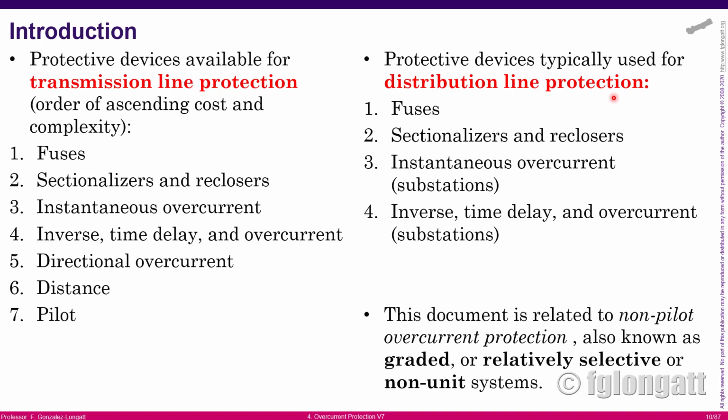discriminate short circuit locations. Again, probably some of my colleagues from the utilities will complain, depending on whether you are using overhead feeders, transmission lines or distribution lines, or underground cables, the short circuit levels can be a big problem. In the transmission system, the main difference is that we have mesh and multiple infeeds. As a consequence, the directionality of the short circuit current starts to be a problem.